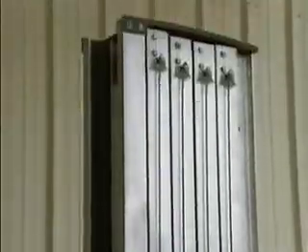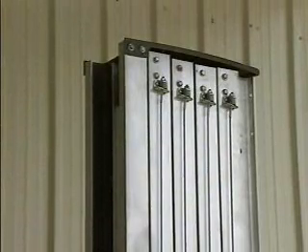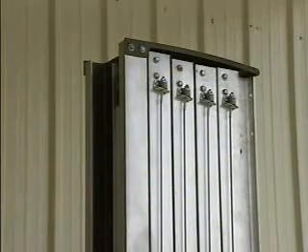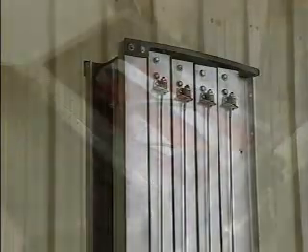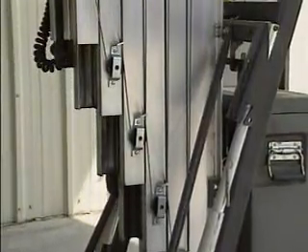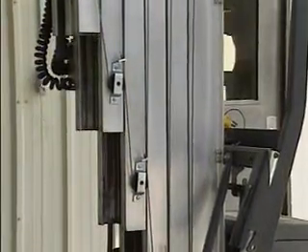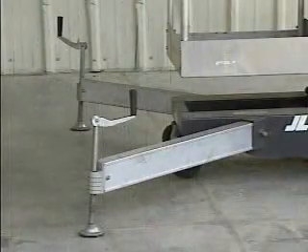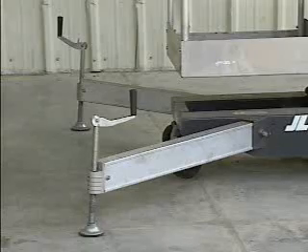The work platform is attached to an upright or mast that's divided into different sections so that it can basically telescope up and down. A battery supplies power to an electric motor, which drives the hydraulic system and enables an operator to raise and lower the work platform. Outriggers that are equipped with screw jacks are used to level and stabilize the scaffold while it's in use.